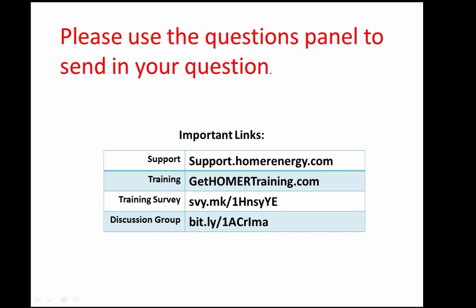Great. Thanks. Is scaled wind speed scaled to hub height? Go ahead, Peter. So there's two different issues there. What you're just talking about is what's often called wind shear, and that's handled on the wind resource page. There's a tab that says variations with height. So you can control your wind shear parameters, a couple of different functions for that, etc. So that is handled, but in a different place.